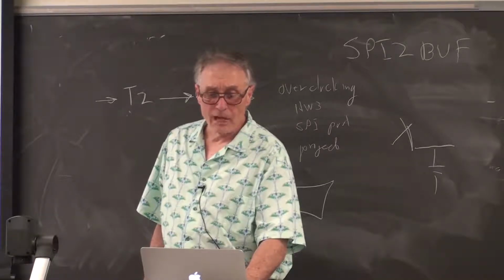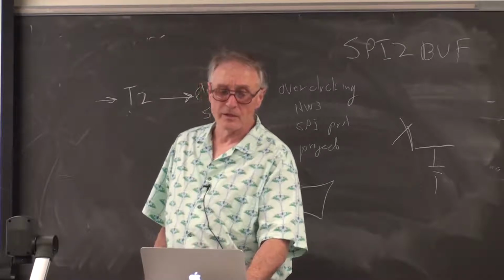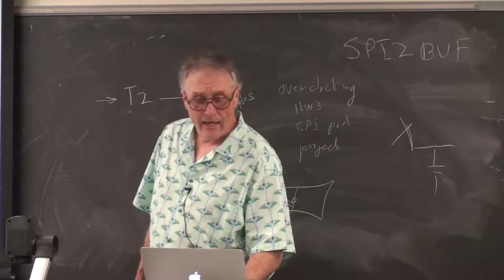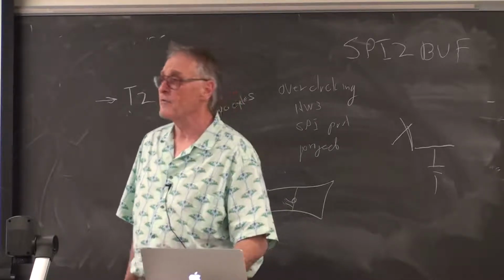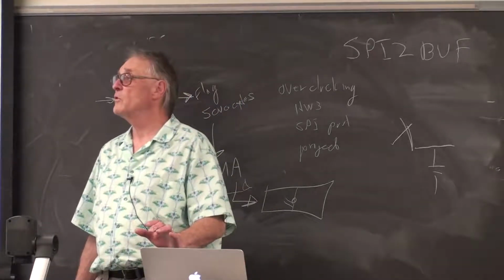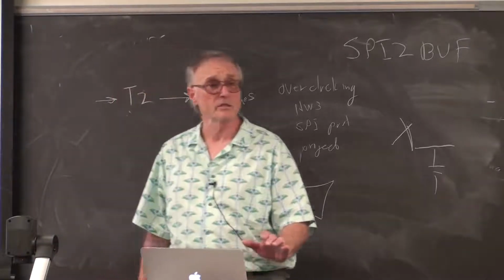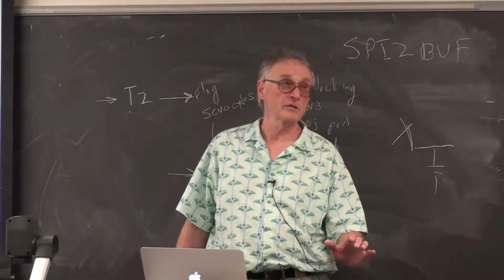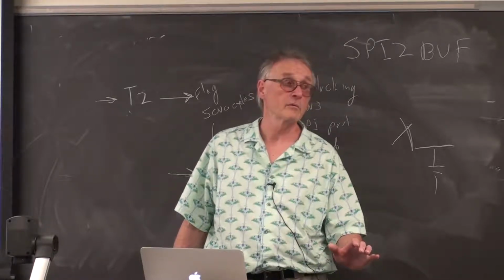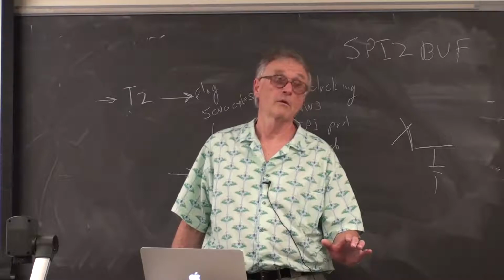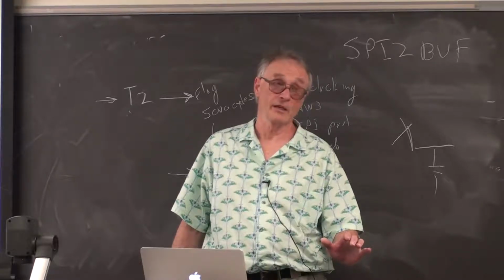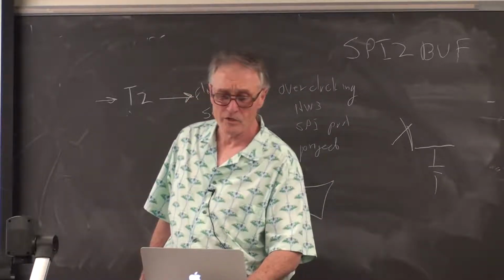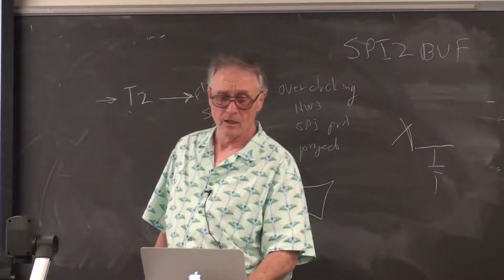Probably going to want to put in a block diagram or pseudocode or something that suggests that you know something about it. Oh yes, also, any RF transmitter has to have reference to FCC regulations. You use a Bluetooth module? I want to see the FCC code section that regulates Bluetooth. It's called Part 15. You'll love it. It is a piece of work. I want you to reference that completely.